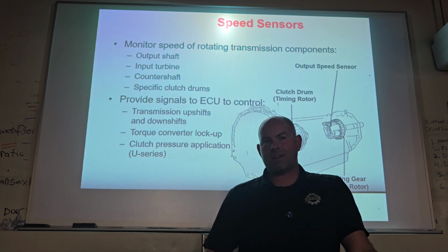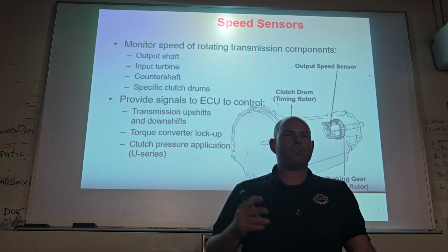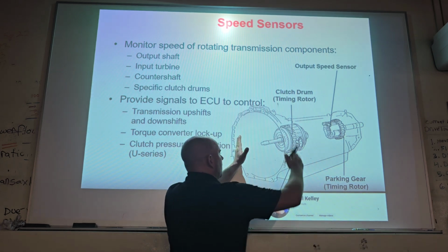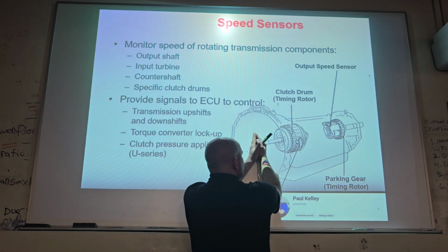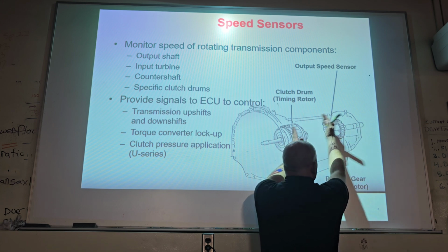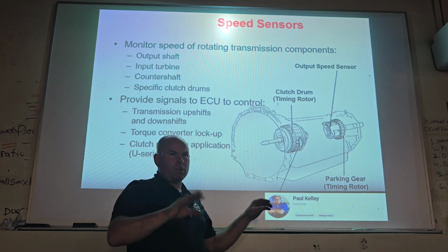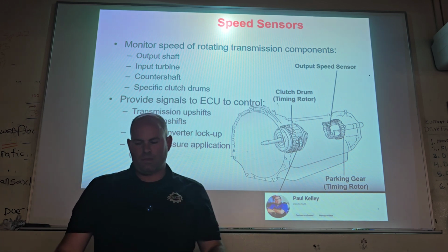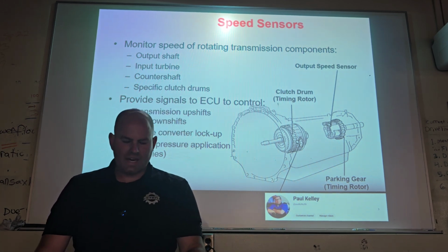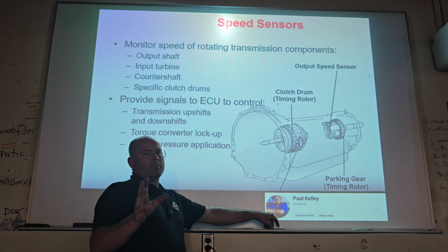I'm telling you right now, it's going to give you different RPMs. It may give you different RPMs between the crank and the input. That would be TCC. It may give you different RPMs between the input and output. That would be holding devices related to the planetary gear sets, but it might only be in certain gears, so, you know. Cool?